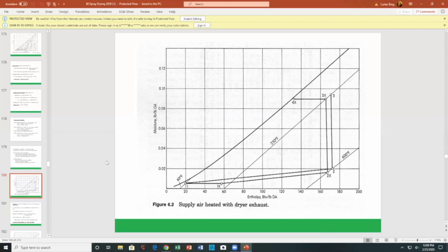So suppose, for example, you want to quickly envision taking your supply air, which was at 60, and you're going to keep it at the same moisture content, but bump it up using a heat exchanger, where you move it from here to there. And you want to see what effect that has. Well, if I project it up and I'm heating with natural gas, basically propane or whatever, there's moisture increase due to the heating requirements. So this line is tilted upward. Now that moisture requirement, with no heat exchanger, you have this situation occurring.